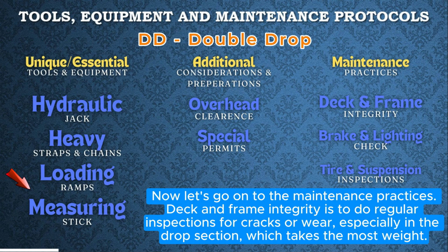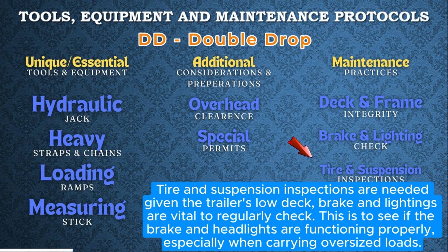Now let's go on to the maintenance practices. Deck and frame integrity is to do regular inspections for cracks or wear, especially in the drop section, which takes the most weight. Tire and suspension inspections are needed given the trailer's low deck. Brakes and lighting are vital to regularly check. This is to see if the brake and headlights are functioning properly, especially when carrying oversized loads.